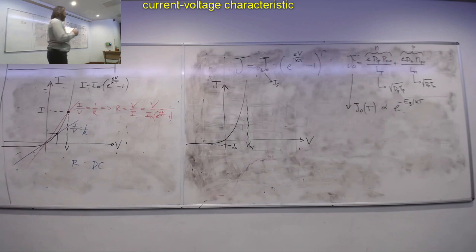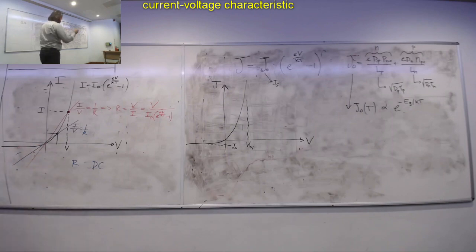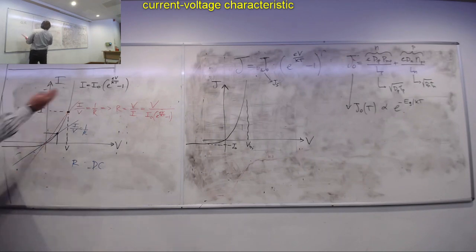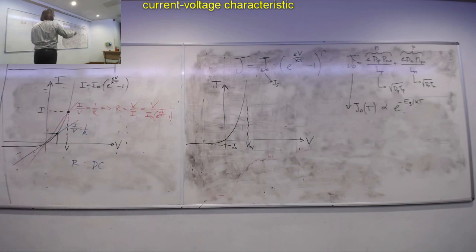It's important because the next thing, which I won't be able to do here, I will put in the post-lecture video. It was the last bit I wanted to do, the differential resistance, which also brings to the diffusion capacitance. So this one here represents the DC resistance of my diode, which is, when I apply a certain voltage, how much current flows through.